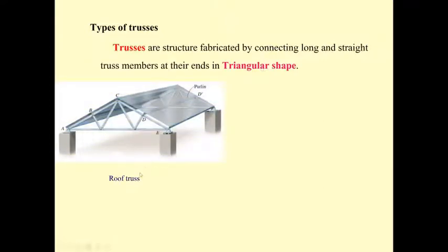And then for roof trusses, most of the time they construct the columns 1, 2, 3, 4. And while constructing the columns, the welder will build the truss on the ground, and then they use the crane to lift the truss into position after we finish constructing the columns.